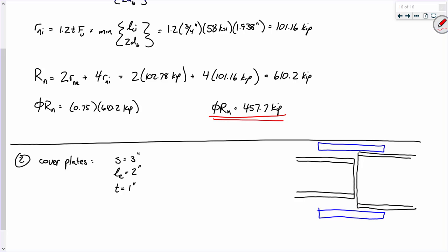So a lot of times what fabricators will do is insert what's called a fill plate to fill up that little gap. It might be something like 1/8 of an inch or what have you. It's not a structural plate and it's not resisting any load. It's just there to get an even surface to splice member A and member B together. So that can happen. But different size splice plates, more often than not, no, you're not going to do that. Does that sort of answer your question? Did you have a question?